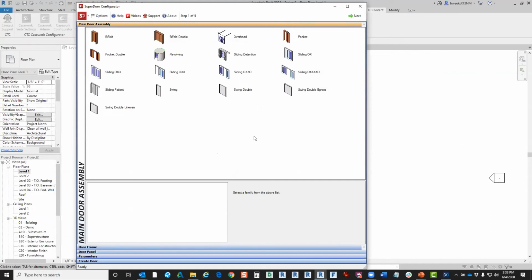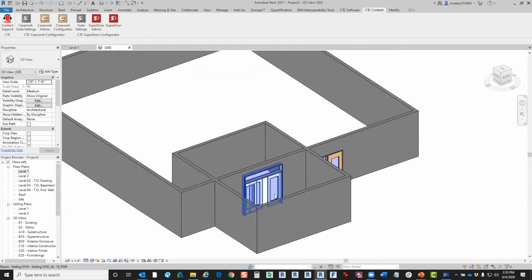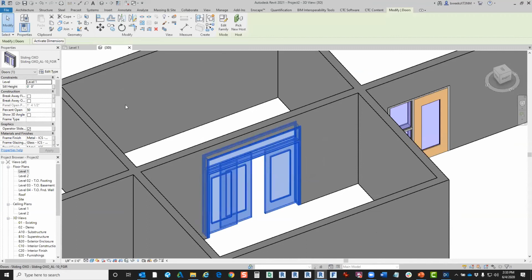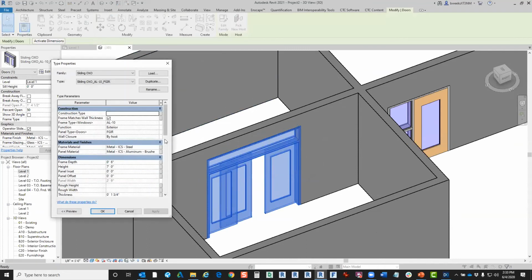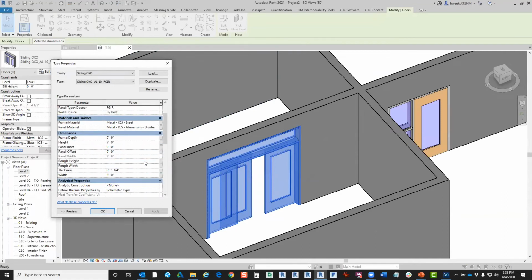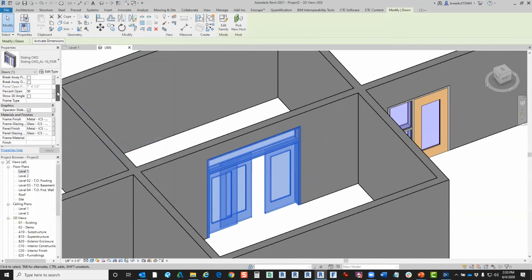Okay, yeah, that's a great one, Jason. How do you control transom heights? So it's actually controlled through the setup the same way as when you're creating it. Now, for example, if I'm using the door I created, I can come in and the properties, you can see that the properties right now are of the entire family of that assembly, I should say. I keep saying family.